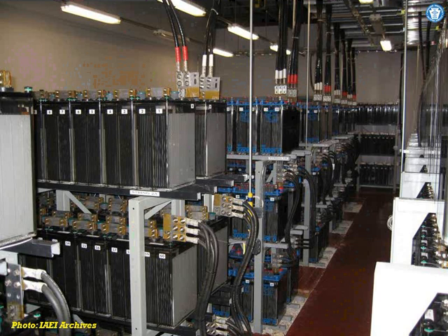Because the UPS has an AC level and DC level. At the DC level, when you take the AC, convert it to DC, you tie your battery, then you invert it back to AC at the right frequency, 208 and 120, and right voltage and frequency. It's a really unique system. The problem is it's high profile, and they have a lot of maintenance, high maintenance on them.